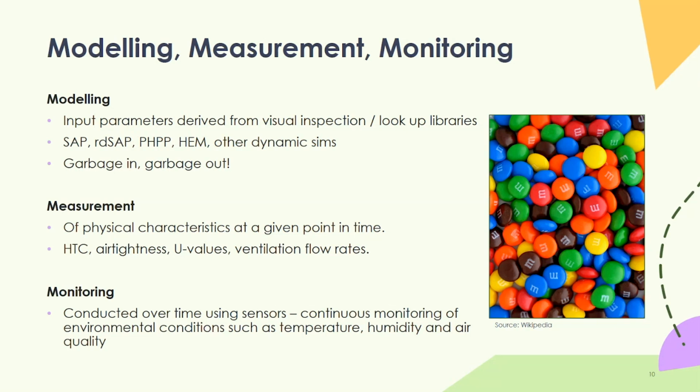Again, I wouldn't advocate that type of monitoring wholly in isolation because, of course, temperature in people's homes is going to fluctuate all over the place. Relative humidity levels are going to fluctuate. Of course, you don't want people to be in extreme cold conditions or overheating or very high relative humidity conditions and then therefore being exposed to mold and condensation risks. But we've got to recognize that all those environmental conditions are heavily influenced by the weather, the occupancy effects, and occupancy behaviors. And so what I'm trying to say with this is that no one of these three things should stand in isolation.